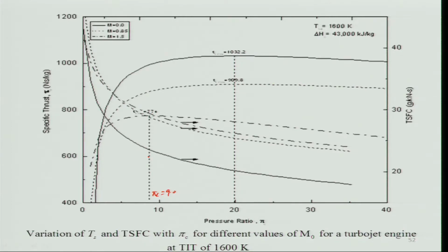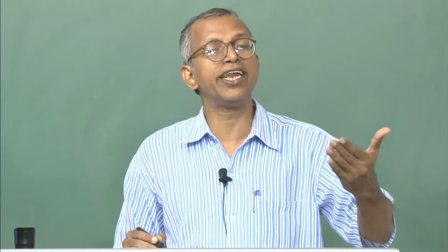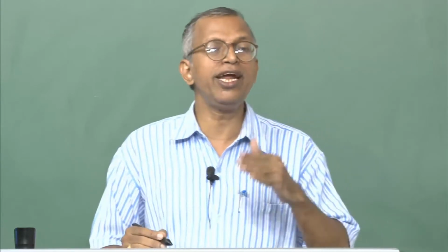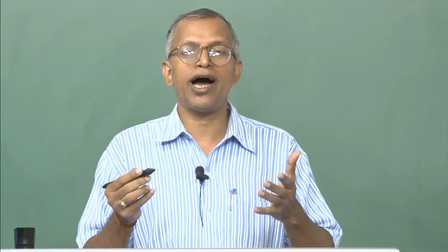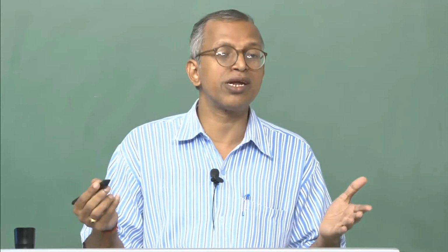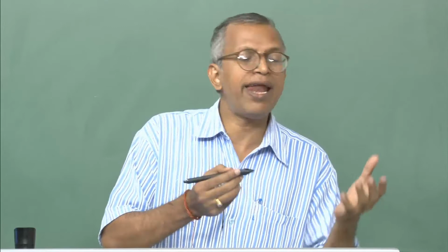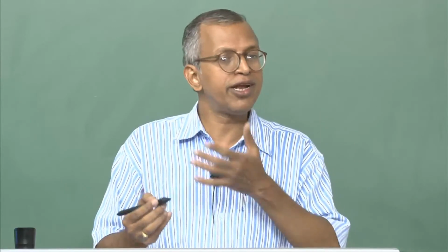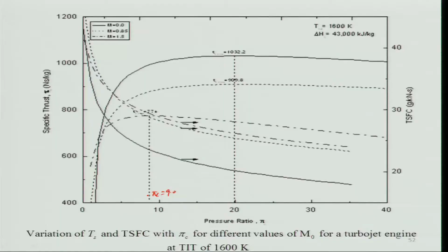What it indicates is that when the flight or the engine is moving at a higher speed, it can use that pressure, and you need not go for a high pressure ratio compression, because the ram pressure can be utilized for increasing the pressure, right? Therefore, if you look at the fighter aircraft, it will have a smaller compression because you need a very low pressure ratio.